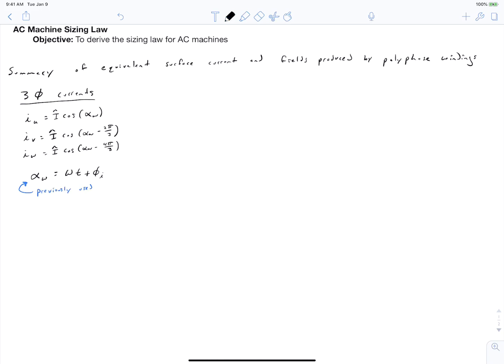And we've talked about going from coils in slots of our stator to creating an equivalent circumferential surface current density on the inner bore of our stator. And we came up with this expression for that equivalent circumferential current density. Now in that video, I was very careful about putting a subscript n on these quantities. It was A_C,n of alpha, where the n indicated the harmonic index. In this case, I'm just tracking the harmonic index in the sine expression, for convenience, because we're only going to be considering the fundamental component. We're only going to be considering the value where n is equal to p, but we're going to prove that. So we're going to keep this as n for now, and then later in the video you're going to see me replace n with p, and I'll point that out to you.